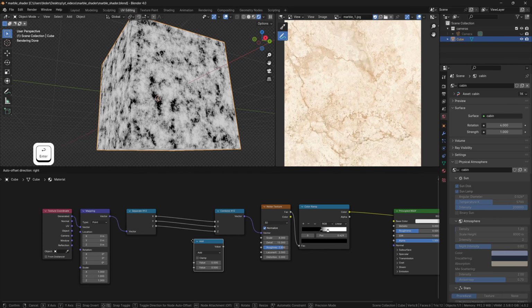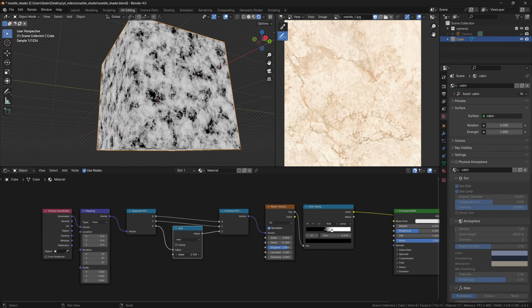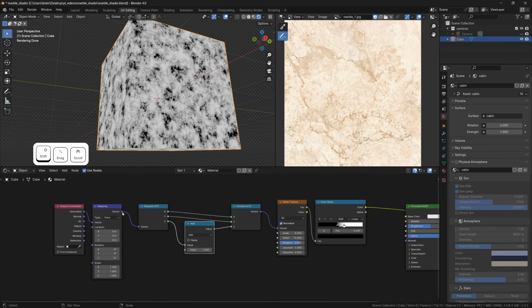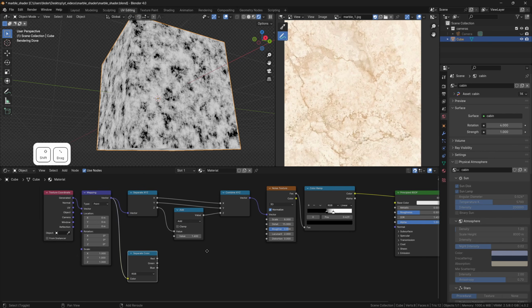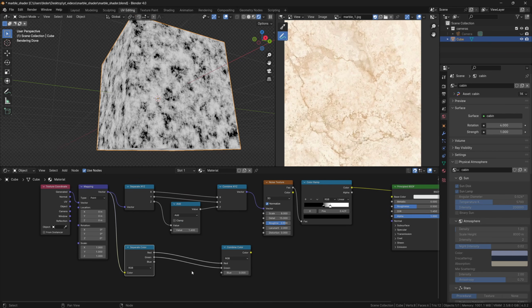Let's say now that we want to move the texture on the Z-axis, we could do so by placing any logical operator in between the Z I/O sockets. And this would be perfectly equivalent to splitting the output of the Mapping node into the three color channels instead, recombining them again and performing the exact same manipulation we just did.